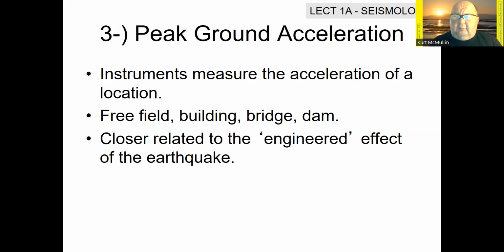What you'll find as you look at these instruments is they're often categorized by what they are installed on. They may be free field, meaning that they're placed at a location which is relatively far away from any man-made structure, but more commonly they're on a building, maybe a bridge foundation or a dam. This measurement is probably the one that's most closely related to how buildings are engineered and how we should design them to be more earthquake resistant.